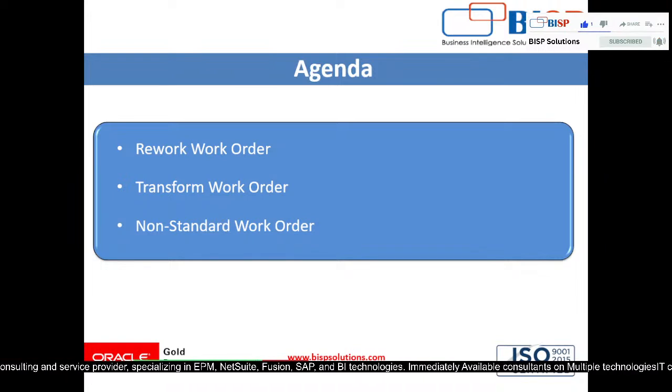And in the next step you can add the operation, you can add the component, you can add the resources for this operation, right? And after an operation you added to the work order, the work order can be released, right? At the end you can release this work order, right? So if your work definition is not specified, the app can update the work order. You can add the operation, resource, item, right? But at least one operation must be added to release the work order.